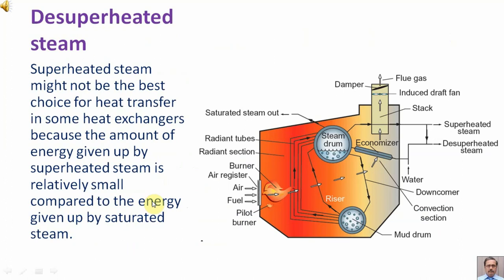Desuperheated steam. Superheated steam might not be the best choice for heat transfer in some heat exchangers because the amount of energy given up by superheated steam is relatively small compared to the energy given up by saturated steam.